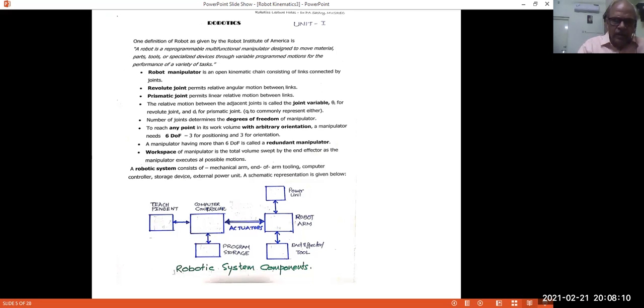And then the gripper operations and all are performed by the teach pendant. The positions of the joint variables at that point are recorded, and then it is again taken physically to another point by operating various switches on the teach pendant, and the positions at that point are also recorded.